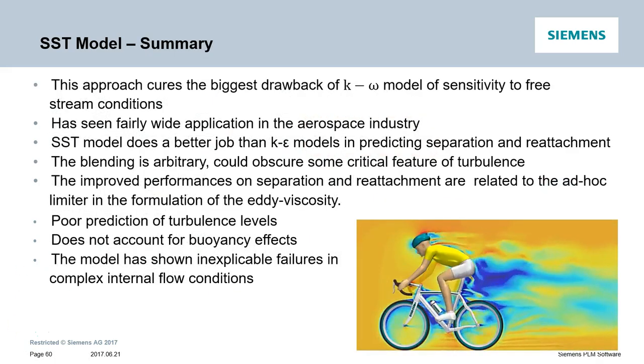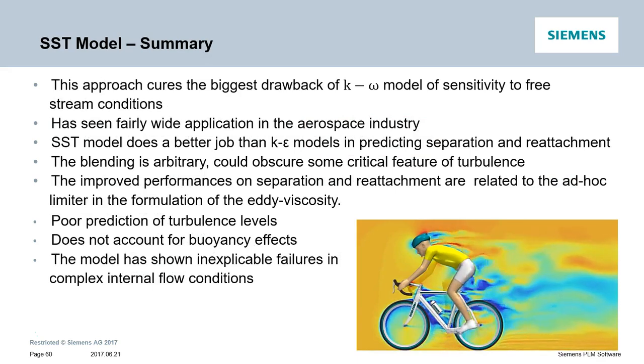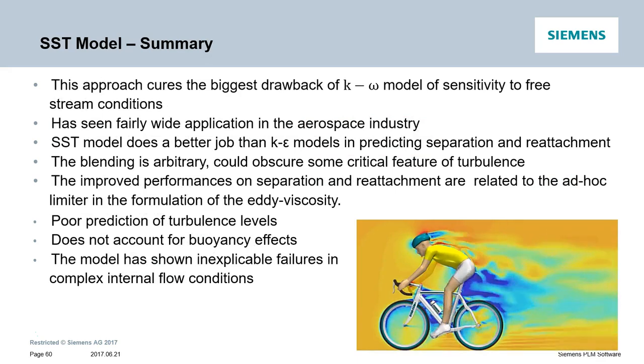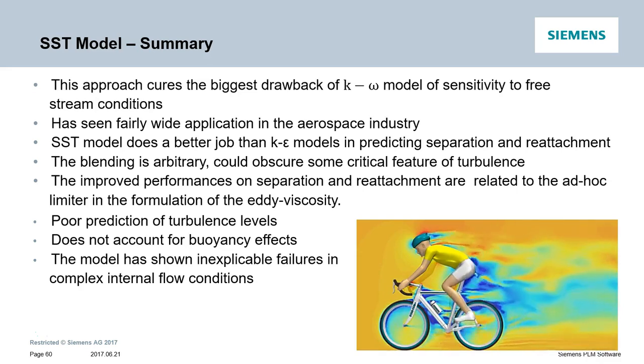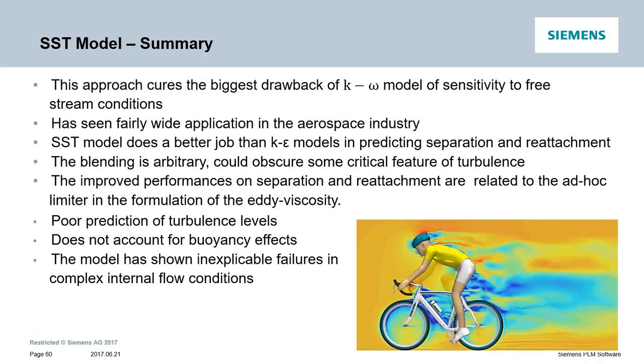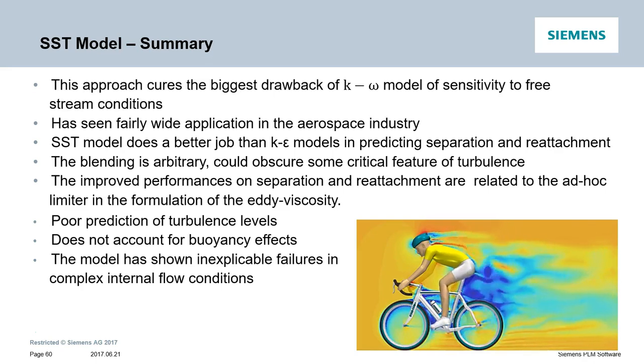So to summarize, this approach cures the biggest drawback to applying the K omega model to practical flow simulations. And this model has seen fairly wide application in the aerospace industry, where viscous flows are typically well resolved and turbulence models are generally applied throughout the boundary layer. And this model has been validated against many other applications such as turbomachinery blades, wind turbines, etc.